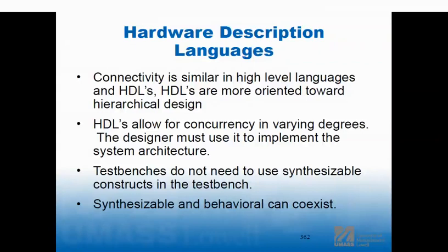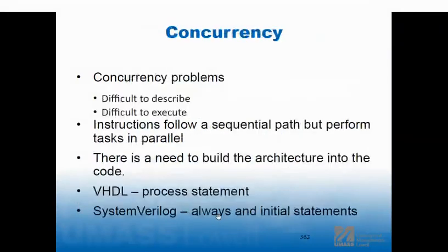When I have 4 state machines running on the same clock in a digital design, they are truly concurrent. I can put in a stimulus on 2 of those state machines, and they will both go to the next state on the next clock based on that new stimulus. That's also synthesizable code, right? Concurrent code that runs in digital logic is synthesizable by definition. In behavioral code, you are running it sequentially.